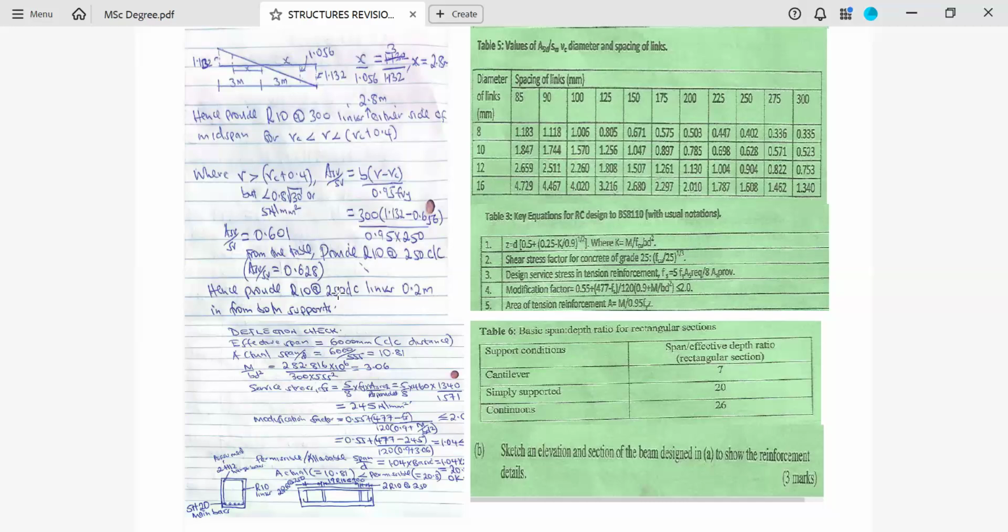are being supported. Because in practical aspect, you cannot have a beam with bars at the bottom only. You must provide hanger bars where you will tie your link. Others call them links, others shear reinforcement, others call them stirrups. It depends, provided the main purpose is to help the beam to resist the shear stress. And then the other view, the second picture, where we have 2R10 at 250 center to center, and then we have 19R10 at 300 center to center.